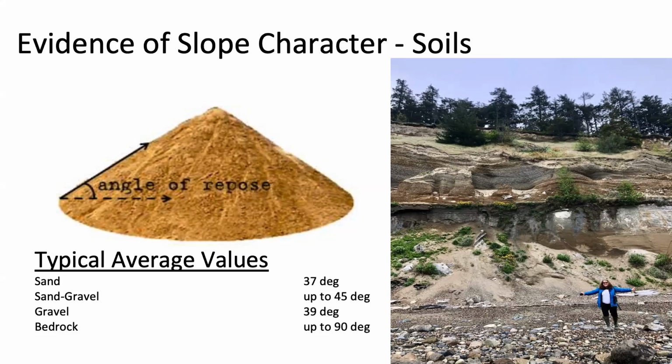One of the key factors that drives the strength of materials and their ability to stand up in the absence of exterior forces, things like a wall or a revetment, would be that soil's angle of repose. It's typically represented by a Greek phi. Really, it's just the angle that a pile of loose soil would slope to and be able to hold a load at.